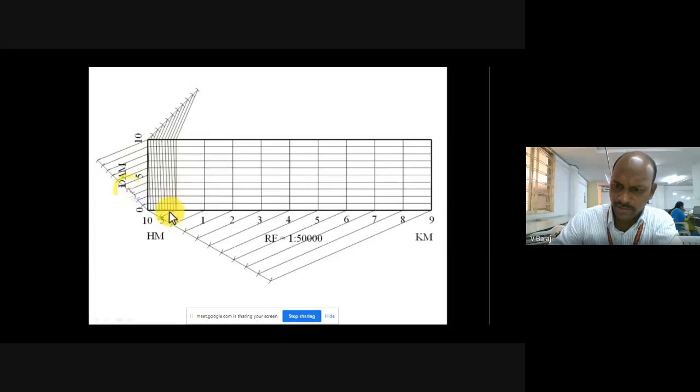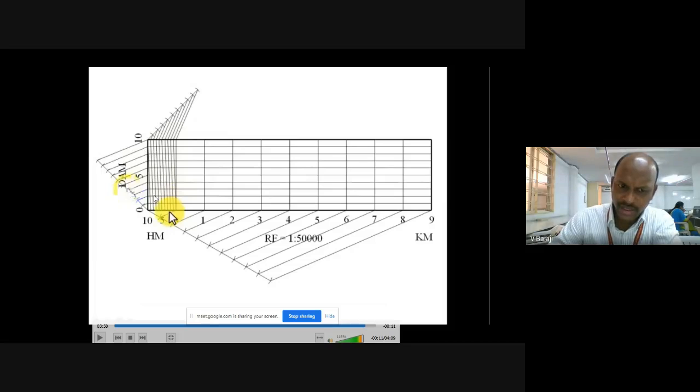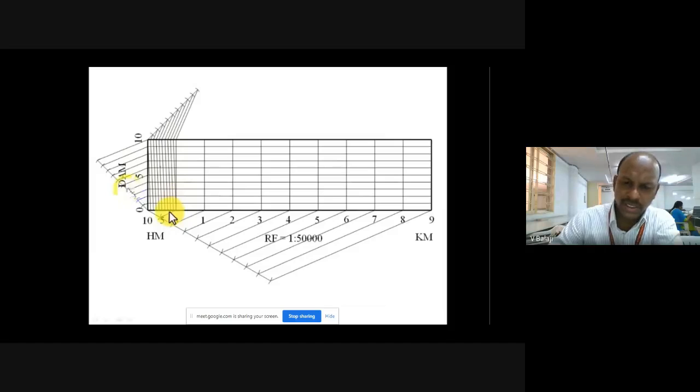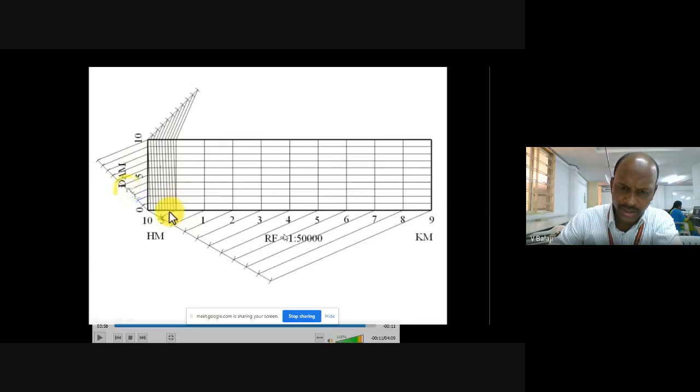I have given you some chart. At that time, don't divide the first part again into 10 parts and the vertical height into 10 parts. You need to see the relation between kilometer, mile and furlong. And if the problem is given in terms of yards, foot and inch, again the relations between yard, foot and inch will be changing, right? Accordingly, you need to divide.